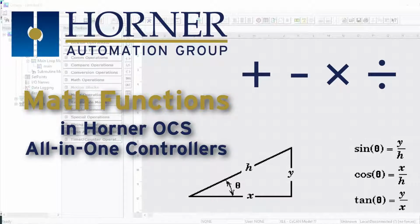So once again, I'm just in the register-based advanced ladder here. Anytime that we are doing any kind of math or anything else that involves function blocks, even if there really isn't any Boolean logic involved in the calculations, we still need to have a contact at the beginning of the rung. That's still a requirement. So we start off with our always on contact, and let's just start out really simple. Let's just throw an add block on here. Okay, so the first thing that you do once you go in to configure a math block of any kind, regardless of how complex.